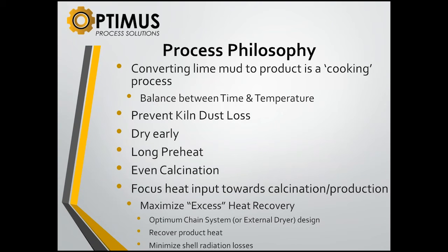The general process philosophy of lime recovery is to convert the lime mud in a cooking way. You must have a good balance between time and temperature. Too long a time, not efficient. Too high a temperature, you will not have a good product. You want to prevent kiln dust loss. In other words, you do not want your feed coming out as dust loss.